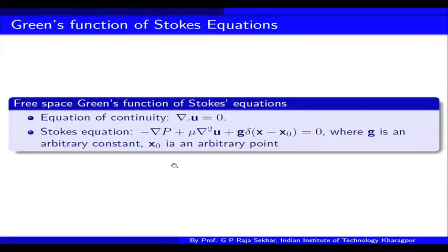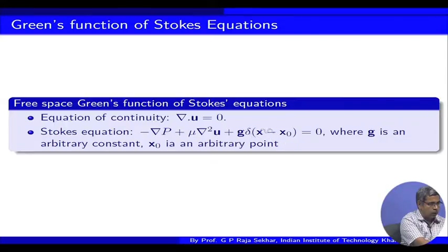So, let us come to the Stokes equation. We have the corresponding mass conservation and then the Stokes equation, but not the homogeneous one. We are considering a point source on the right hand side with a strength z bar. Now, we would like to compute the singular solution of this. If you recall, in week 3 we discussed the singular solution of Stokes equation, but restricted to irrotational flow, that is, due to potential flow. Now here we would like to discuss arbitrary singular solutions of Stokes equation.